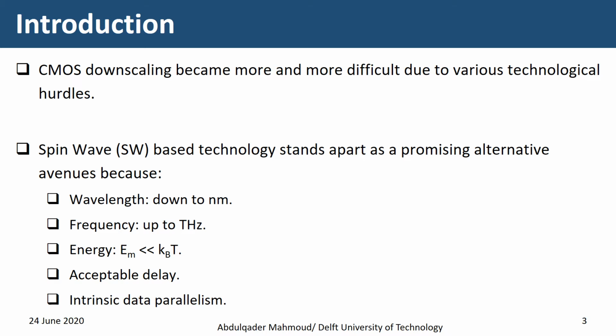Different logic gates have been proposed in the literature. However, this magnetic technology provides only one output, which cannot provide fan-out capability. Therefore, if the output of such a gate should be fed to multiple following gate inputs, it must be replicated multiple times, which results in substantial area and energy overheads. The problem of fan-out is solved in this paper, and a multi-input, multi-output programmable logic gate structure is proposed.